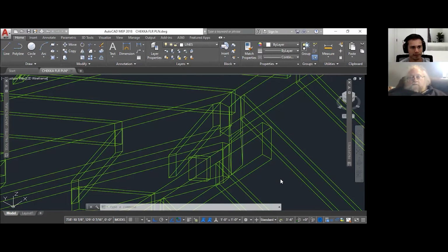We left off talking about fill rafters, but today I'd like to expand a little further and talk about continuation hips. It's a term that I've used a lot over the years. I'm not sure how prevalent the term is, but when we say a continuation hip, we're talking about a hip that cuts off where it hits the ridge below it.